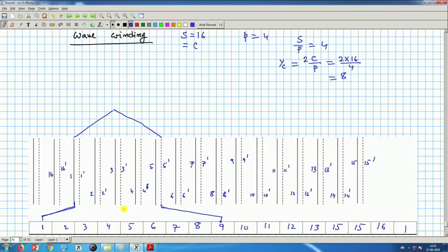Will it change the induced voltage magnitude? No, induced voltage takes place only in the coil sides. These are outside the magnetic field, north south here. These are overhang of the coil. So, it will be terminated here. That is the commutator pitch, this is YC, 2 pole pitch apart.